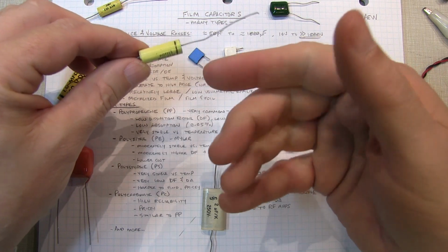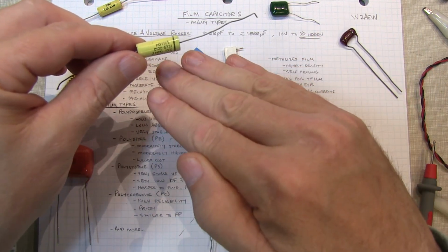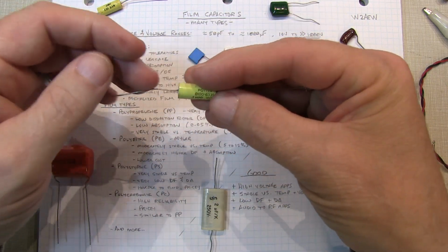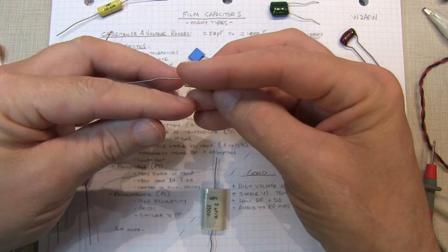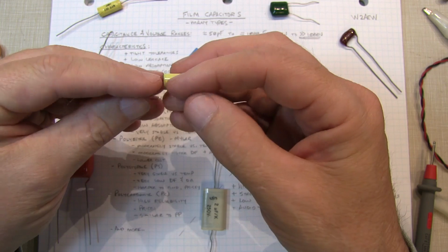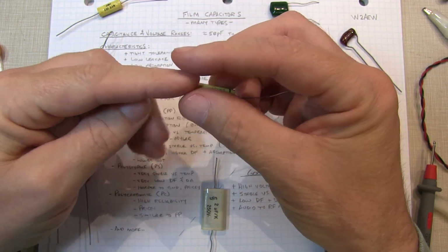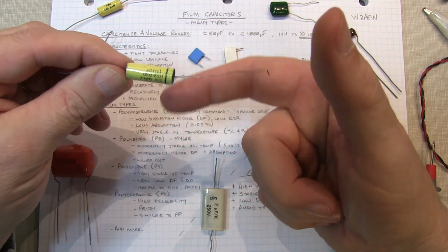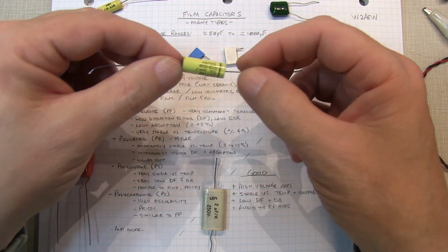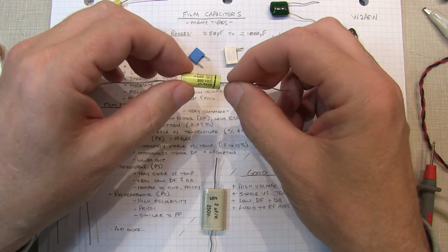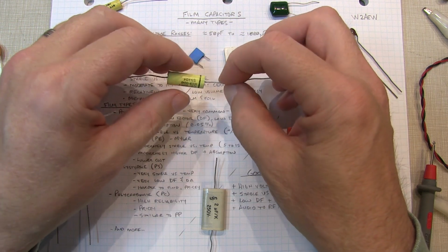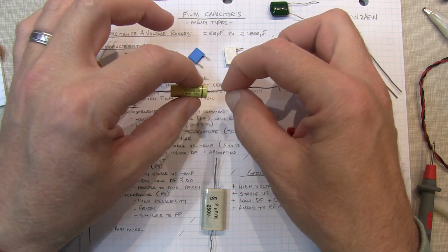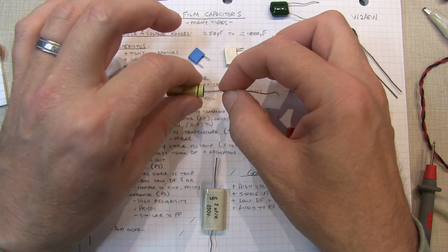So if you think about it, you've got basically an insulating layer and a conductive layer that are wrapped up. So one of the conductors is going to be on the inside of that last wrap. The other conductor will be on the outside of that last wrap, with the insulator being in the middle. So the band indicates the outer wrapping is connected to that wire. And oftentimes in electronics, what you're going to want to do is connect that to the lowest voltage potential in the circuit, so that you don't have a high voltage on the outer perimeter of here.